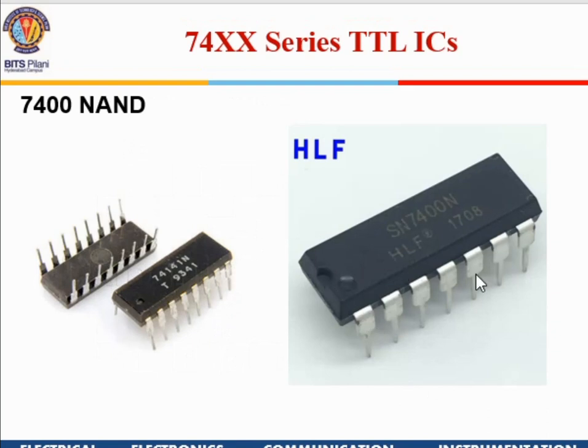You will find there is a notch here, there are pins available here. Various companies, TI, Fairchild, everybody manufactures this 74 series of gates. Essentially the pin configuration would remain the same. The brand could be anything, but more or less the functions and pins will definitely be the same. They might differ a little bit in terms of their speed of operation and power consumption. Otherwise, 5 volt TTL is fixed. The pin configuration for these ICs will be fixed.